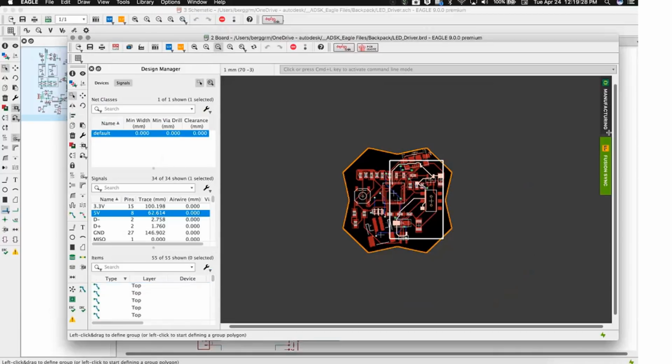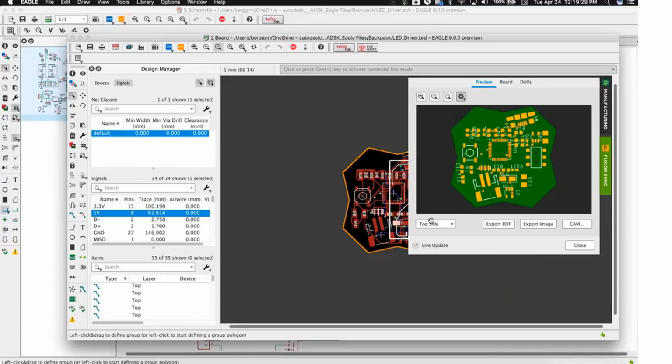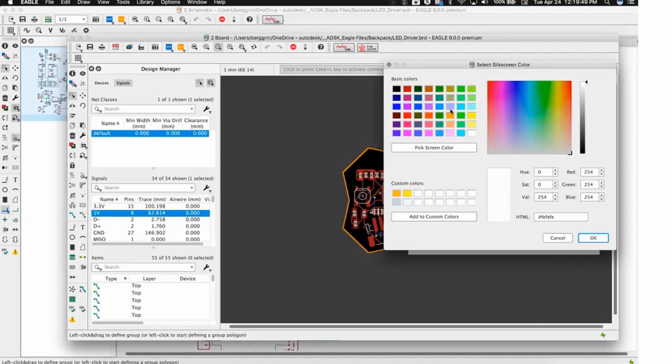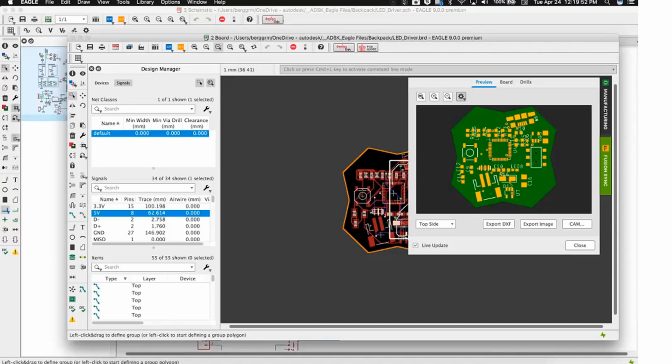Yes. Okay. You can control it. You can hide it where it's at the top, I think, right? We can change the color or something. Yeah, so you can change the color. It's still pretty suboptimal. I think we can do a better job of hiding the silkscreen color if you wanted. So yeah, you could pick an existing color like the green that's being used in there. I tend to do a lot of boards with a black background and white solder mask. Just a shout out to my friends at Hackaday.